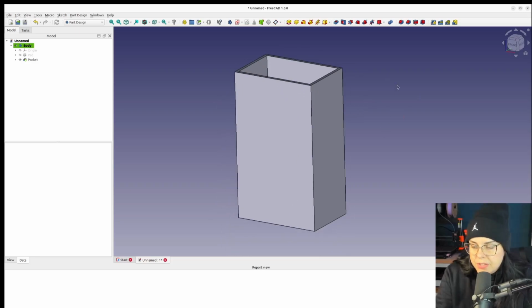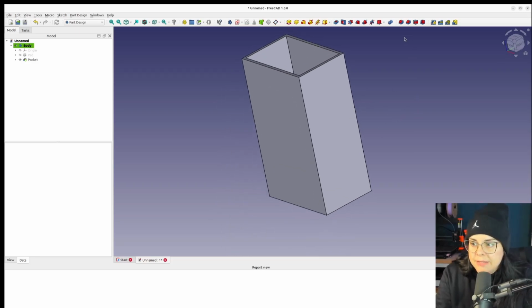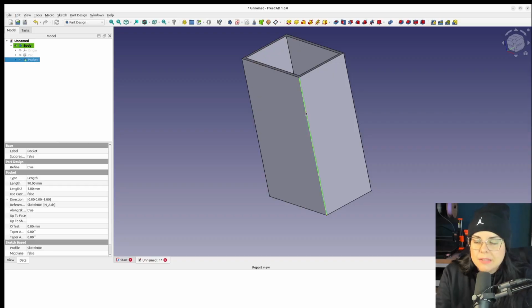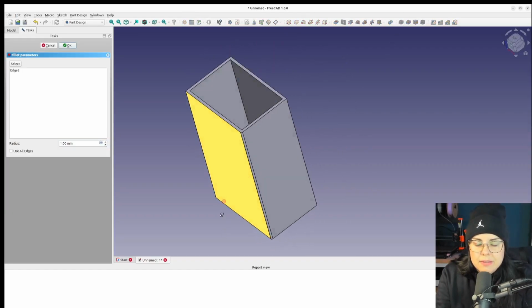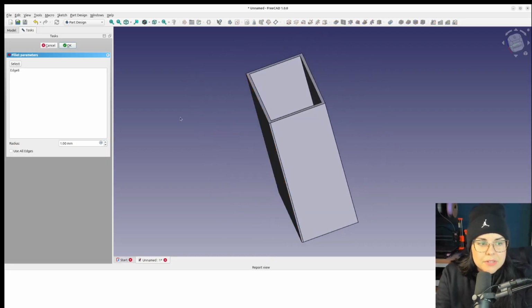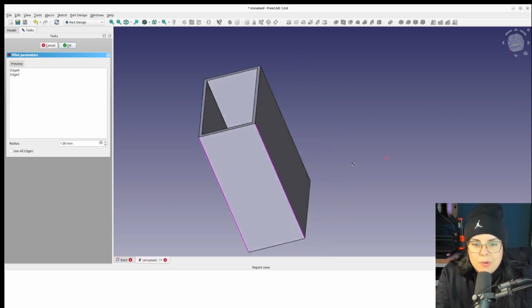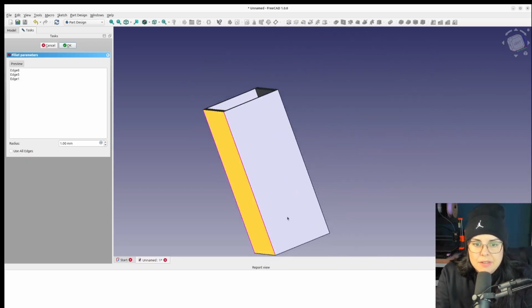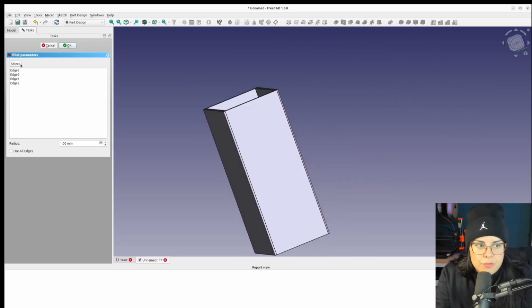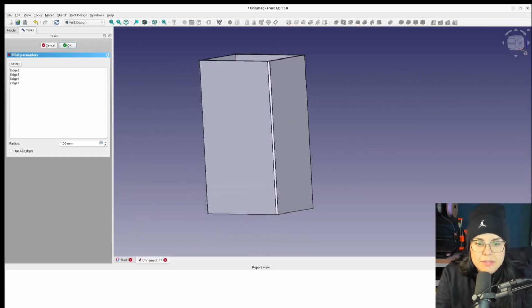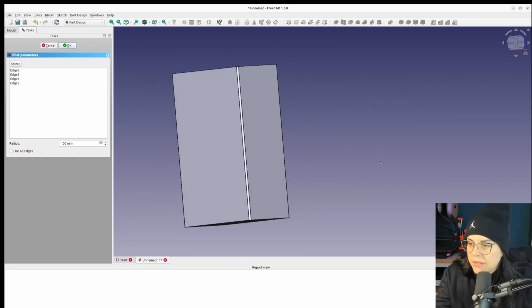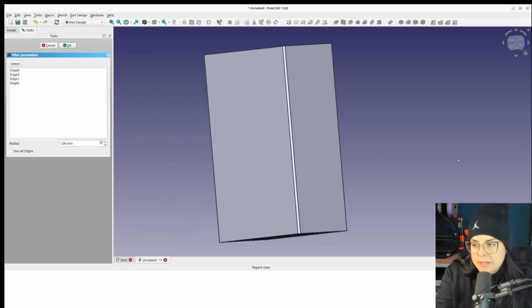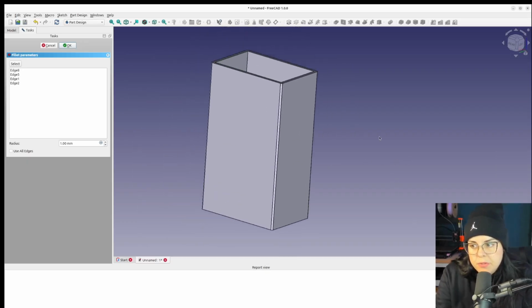And so to finish this, we can do a fillet. Select the corner, and then select the fillet tool. So it's gonna slightly round the corners. Then click on select, so you can select more corners, all 4 corners of it, and here. And then you can preview to see how it's gonna look. And this way you keep the bottom all flat, and that is easier to 3D print. The top and the bottom remain flat.